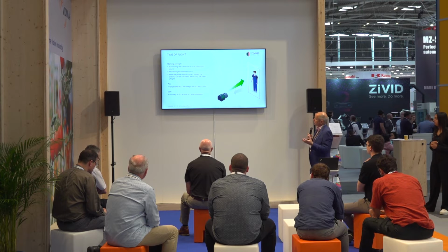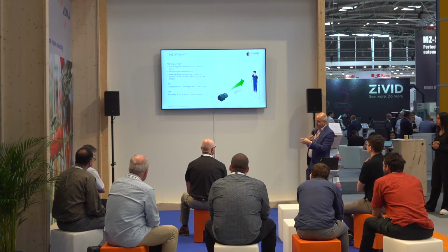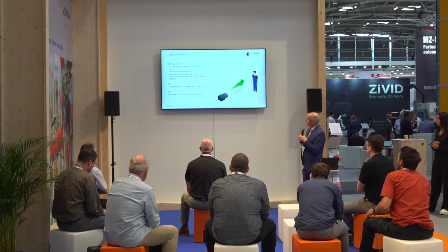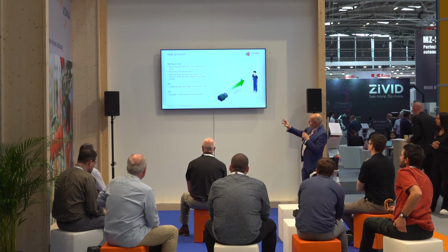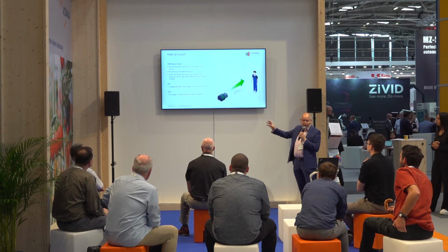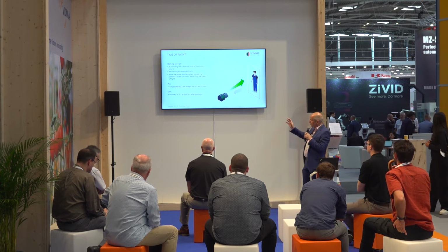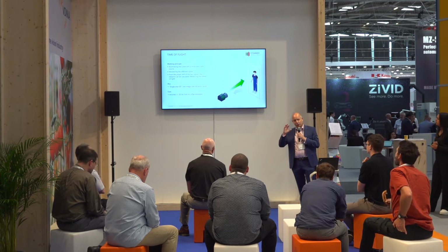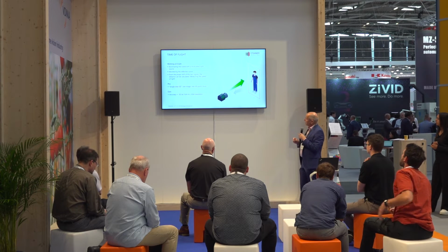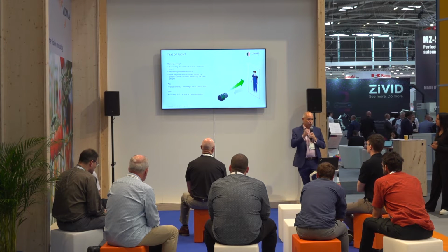It is susceptible to things like light, because obviously that light that's being projected mustn't be smothered by the environmental light. You get a single shot image. Accuracy, though, we are only talking about 1 centimetre, half a centimetre about, and probably at the moment we're talking about VGA resolution, might be getting to megapixel at the top end. And quite often a lot of them are less than VGA, a quarter VGA.